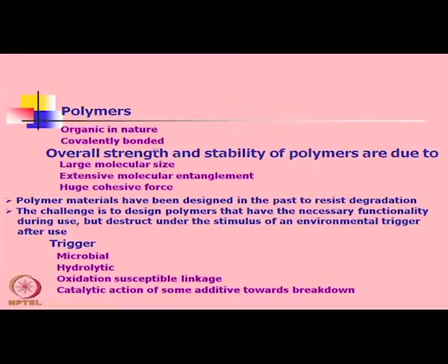Now, these polymers are organic in nature. These polymers are covalently bonded, primary covalent bonds are there, and in the product form, apart from such primary covalent bonds, there are huge secondary van der Waals bonds which make such polymers very strong and tough.